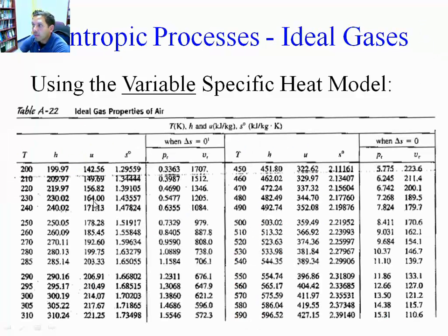Let's go to a table right away. These are the tables of ideal gas, for example, for air. Notice that it's only a function of temperature. It is not like the tables for pure substances where you have to go with temperature and pressure to extract the rest. In this case, you go in with temperature and extract the enthalpy, the energy, and now this value called S0. Remember, S0 is not the entropy, it is a component of the entropy. So you have to complete the equation. The entropy change from 1 to 2 is the S0 change minus R times the log of P2 over P1.